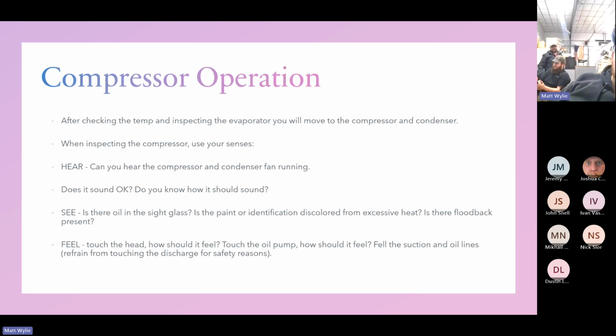Is there oil in the sight glass? Is the paint or identification discolored from excessive heat, or is there flood back? Back to the paint: I had one of the compressors at Costco. The head of it wasn't the same color as all the other paint, and it got really, really hot.